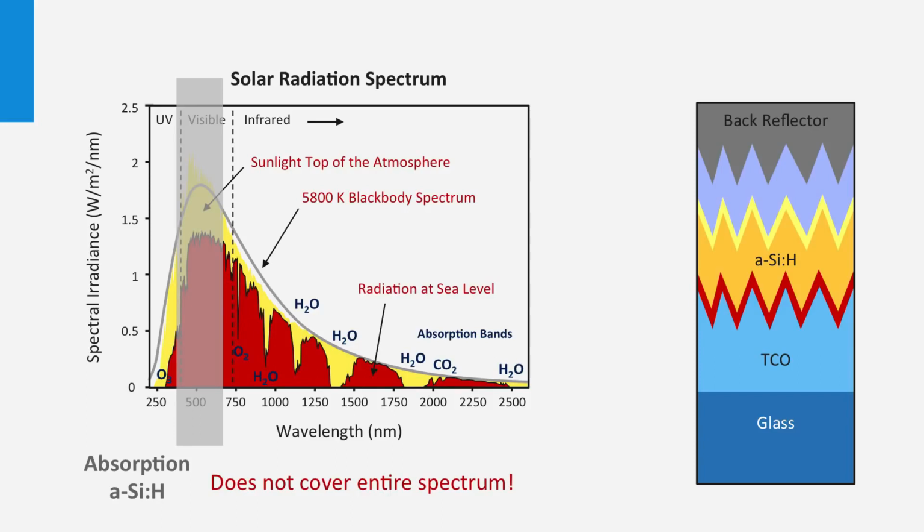The best open circuit voltages are in the order of 1 volt. With respect to a bandgap of 1.75 electron volt, the bandgap utilization is relatively low due to the high levels of Shockley-Read-Hall recombination and the relatively broad valence and conduction band tails. The best stabilized efficiency of a single junction solar cell is 10.1%, obtained by the research lab of Oerlikon Solar, currently part of Tokyo Electron.